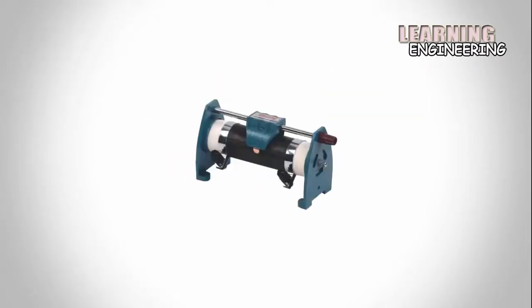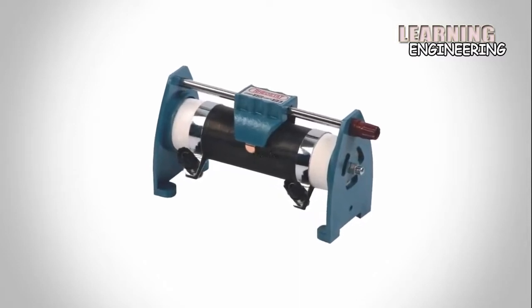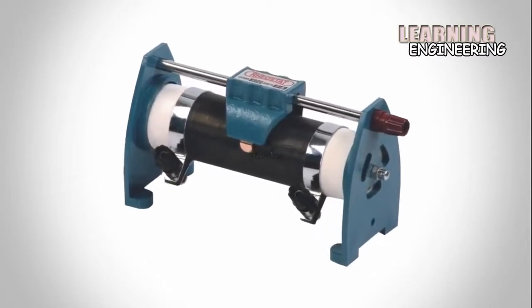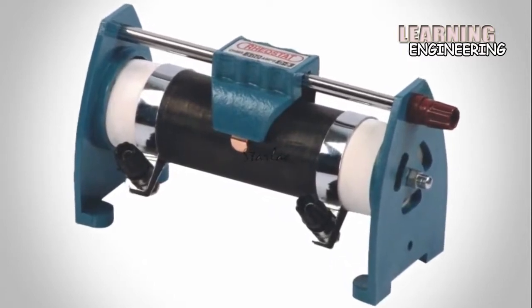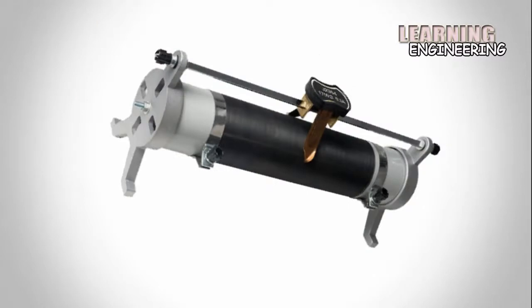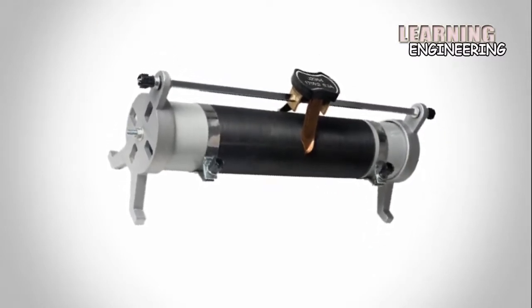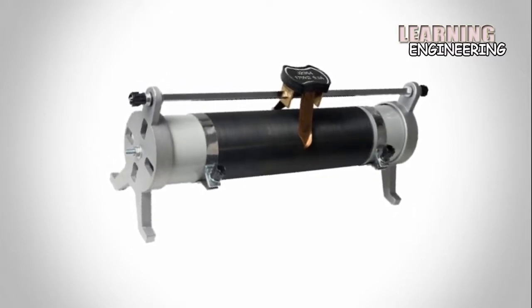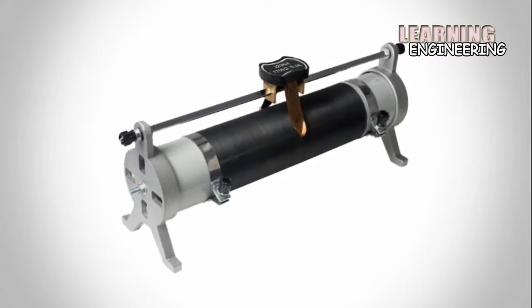Rheostats. Rheostats are a 2 or 3 terminal device which is used for current limiting purposes by hand or manual operation. Rheostats are also known as tap resistors or variable wire wound resistors. To make a rheostat, they wind the nichrome resistance wire around a ceramic core and then assemble it in a protective shell. A metal band is wrapped around the resistor element and it can be used as a potentiometer or tap rheostat.